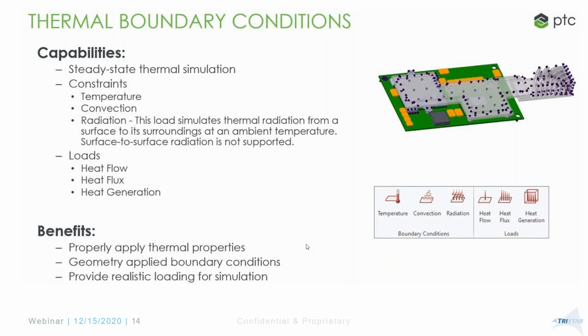Transient thermal is not yet available, but that's something maybe in the future. But right now with 7.0.2.0, remember this is the first initial release of Creo 7, date code 7.0.2.0, that the Creo ANSYS is there, and so you might see more and more enhancements coming up in the future. But you can apply temperature, convection boundary conditions, radiation, right? You can apply an emissivity, right? A few things are not supported, surface radiation, but those might happen in the future.